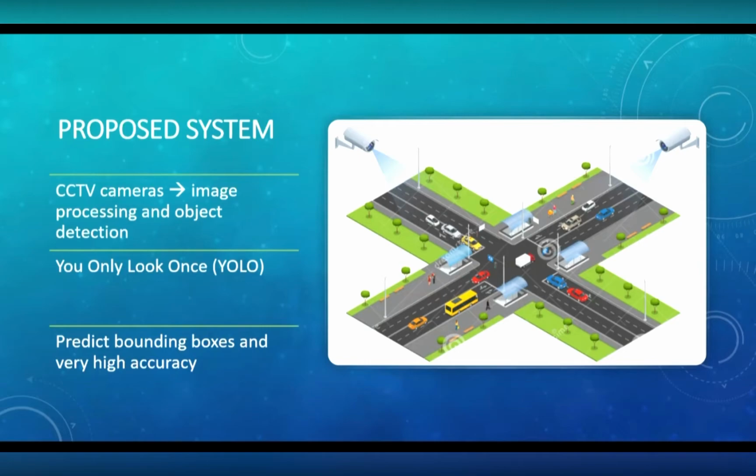For the traffic light management, the traffic density is used to calculate the signal switching time. It uses some other factors too to set the green signal timer for each lane. The red signal times are updated accordingly. To avoid starvation for a particular lane, the green signal is restricted to a maximum and minimum value.